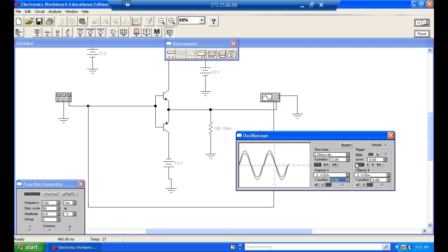Yeah, we got 1.4 volts, right? 7/10 of a volt on top, 7/10 of a volt on the bottom. That's good. But this is what it takes to turn it on right here. Here's the 7/10 of a volt that it takes to turn it on. So let's move this guy out of the way. If we do it like this, we end up with what we call crossover distortion, which means right here where it switches from one side to the other. Can y'all see what I'm talking about? Now, if we looked at this on a real amplifier, it would be flat right there where it crosses over.